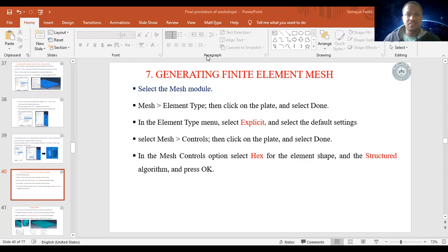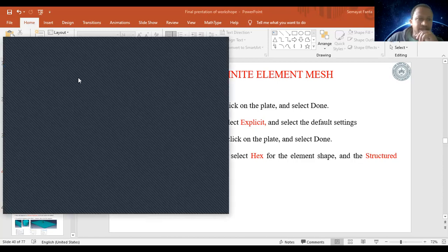How can we do that? For example, the interface material is a cohesive material. For that, I have to assign cohesive property. So assign material, then click on this, and then we can see here standard and explicit. So it has to be not standard but explicit, and the material type is cohesive.